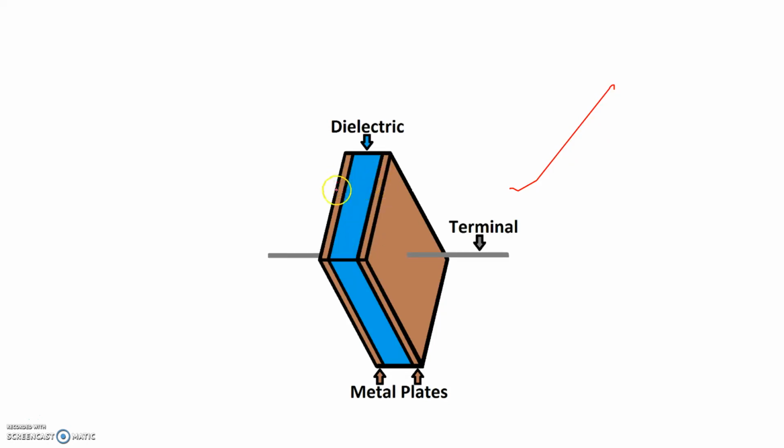See, two parallel plates which are basically conducting, through which we connect the terminals or wires, and in between the two parallel plates there is dielectric, and here comes the disadvantage produced by the capacitor. The dielectric is dependent on temperature. What is the dielectric formula for capacitor? Epsilon naught into epsilon r. Okay, where epsilon naught is obviously the permittivity of free space, and epsilon r is the relative permittivity and it depends on the temperature. Okay, so in this way the capacitance also depends on the temperature.